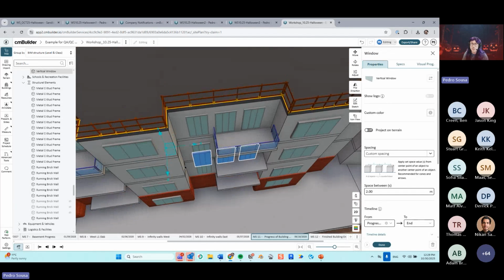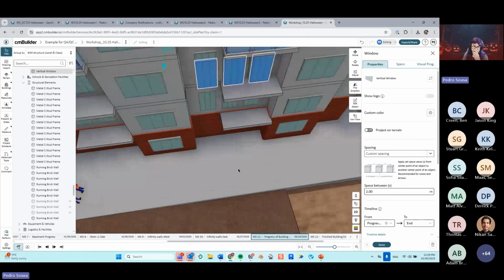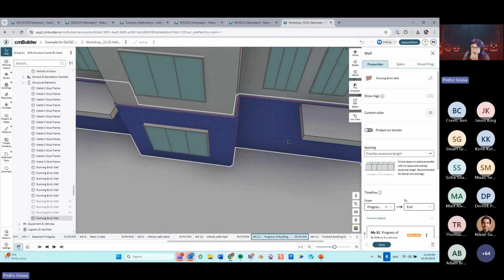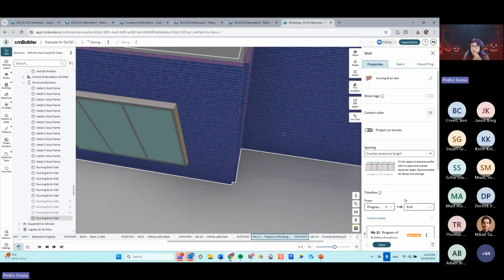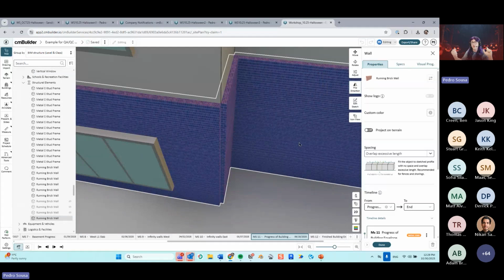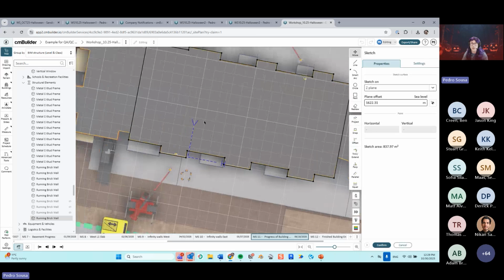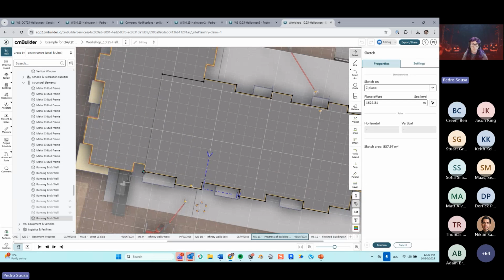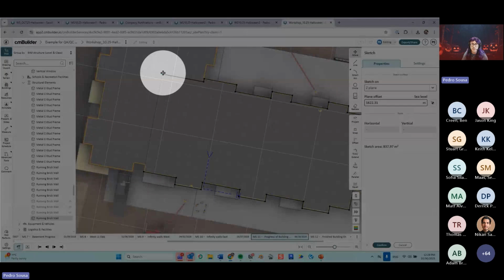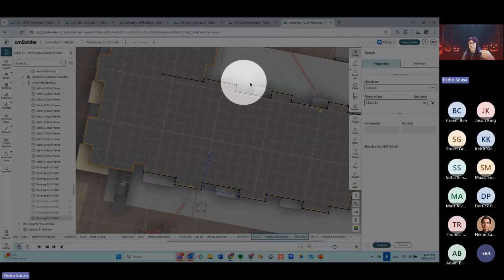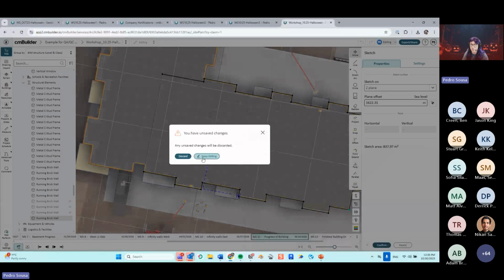Sweet, for your question, no, because if you do that flip, actually let's try. If I flip the direction, no, because the flip the direction is only going to start the pattern from one point of my line. Instead of starting on the point on the left, it will start on the point on the right, for example, right? So if I open the sketch over here, instead of starting from this point, it's going to start from this point, the pattern running from here all the way to the end. So this won't fix that little corner.